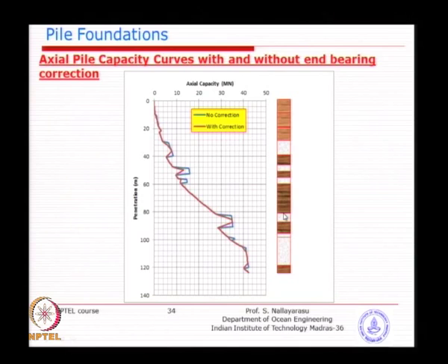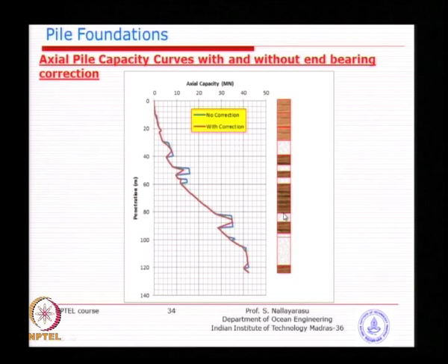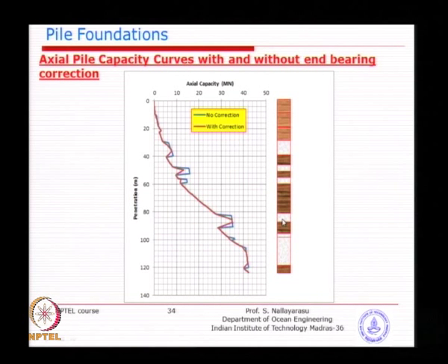Now, you have a lesser penetration, number 1, and this layer is not too large for you to take the capacity, because it is only a small, say 3 meter or 4 meter layer. Now, there is uncertainty whether that layer is there or slightly lower, whether the thickness is 3 meters or whether the thickness is 2 meters. If that happens, can we take the capacity of that layer in full, or can we take a reduced capacity, because there is an uncertainty?